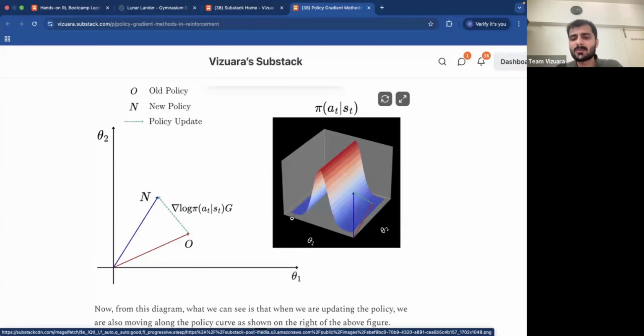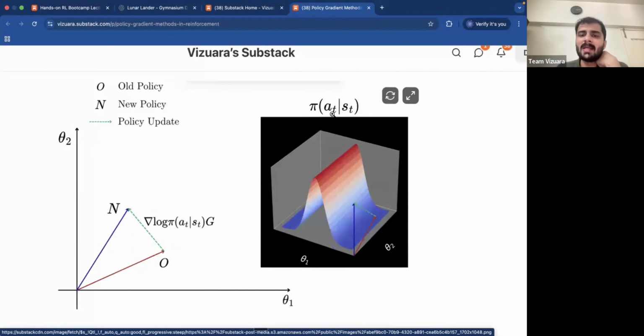the policy which is used is parameterized as a neural network. What the policy essentially gives is, for every state which is denoted by s_t, the probability of taking an action a_t. Let's take an example of the SO101 arm with 6 degrees of freedom. In that case, we have 6 possible actions as an output. And for every state, this function will tell me a probability distribution across these 6 actions.